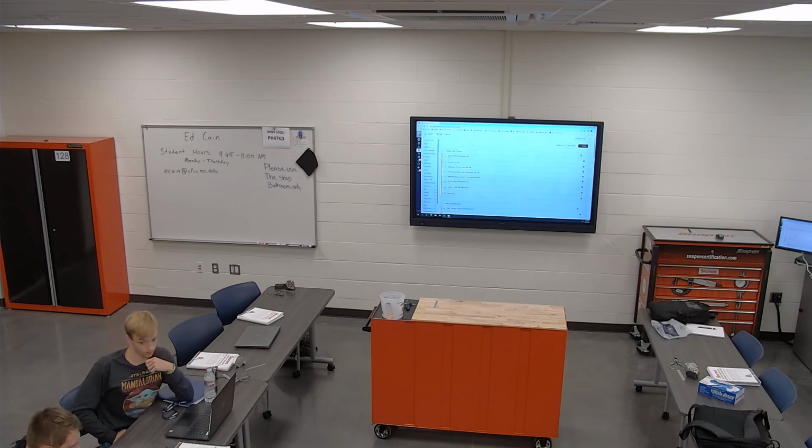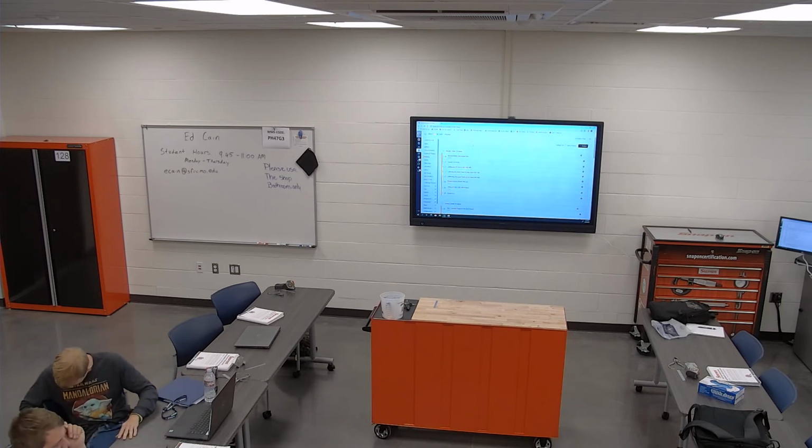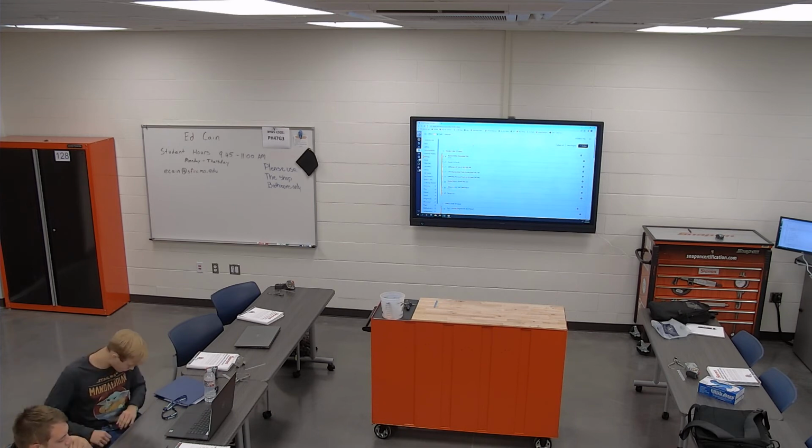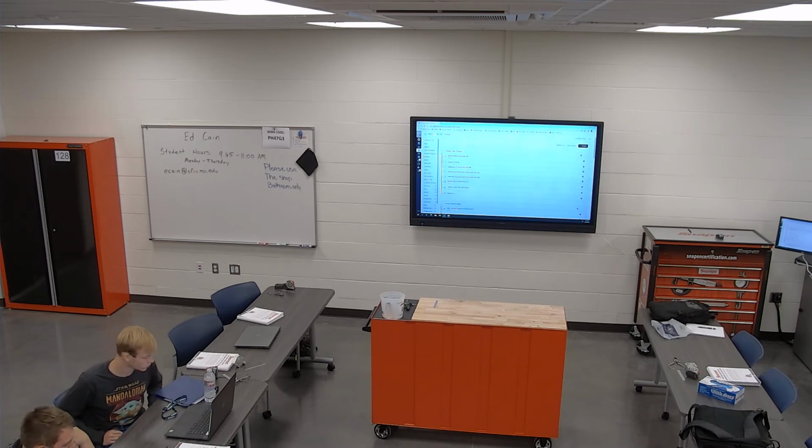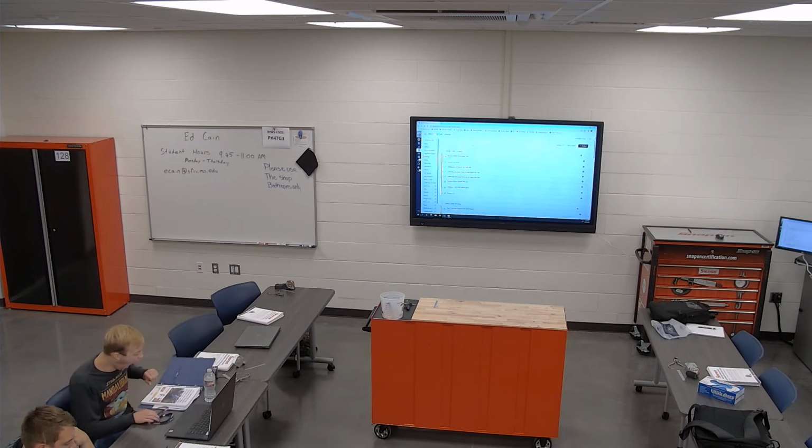What do you want it to do, exactly? Make a list of what exactly you want it to do, and then go over solving everything on that checklist. I think the program, like the one I have, would work. You can just mill one side and flip it around, and then just make sure you get both sides clean. For the second side of the program, you just change some of the dimensions so it fits. I'm just gonna clean up the sides manually, just run it across, and I'm not gonna try to do any special tricks with it. Once it's down to size, I'll throw it in, and then it should be fine.